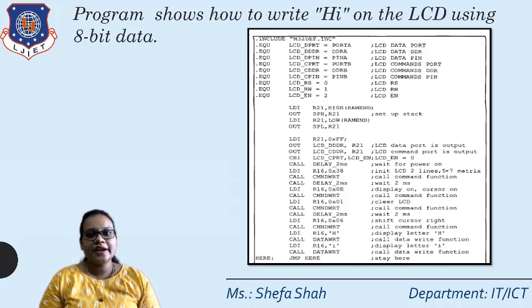Then for initializing, we need to give a delay of 2 milliseconds. This 2 milliseconds delay will be called using the call instruction, call delay_2ms.